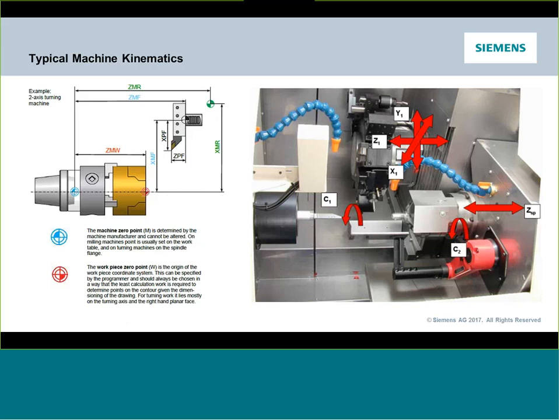Well, that's still going to be based off an offset of the main spindle. So if you start to look at how all your zeros or your offsets stack, they're going to be stacking up off of the main spindle. Now, from a tooling perspective, the turret is going to be datumed in relation to that main spindle, and there'll be a fixed location on the turret that is its primary 0. So the tools, as we get into using the tool offsets, are going to be physically the distance from a gauge line or the turret datum to the tool tip.